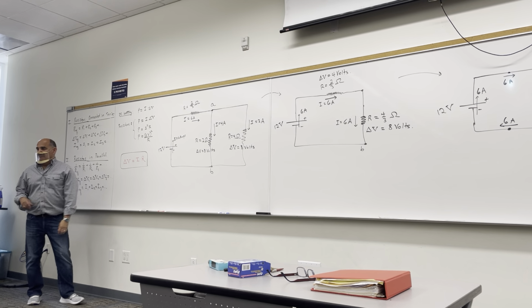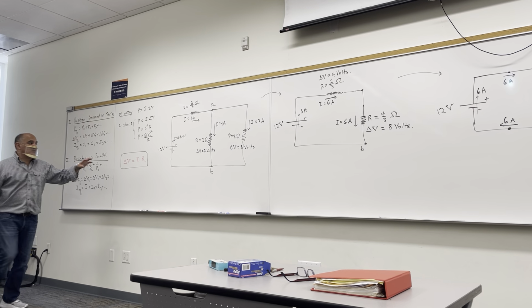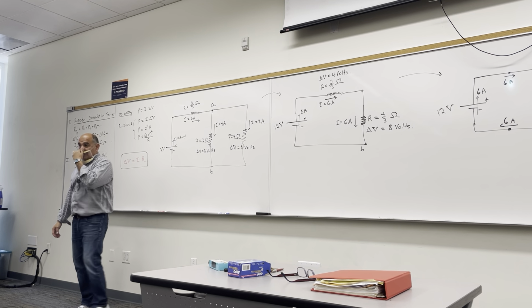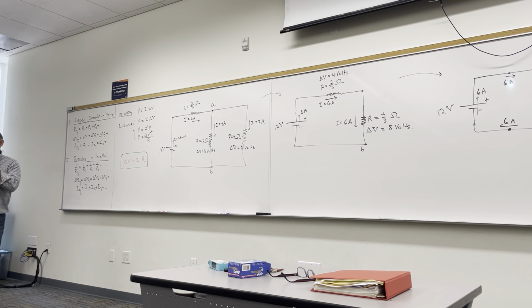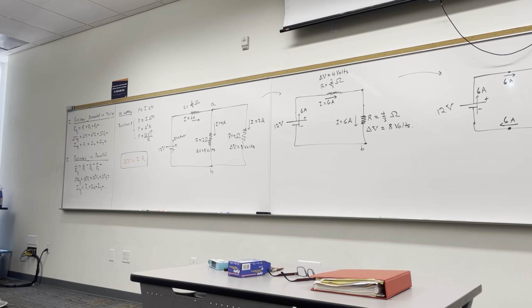Any questions? On the exam, do you want us to just draw that, or do you want us to box the answer? I'll give you the circuit, and you'll have to figure it out. By drawing it, it helps. Do you want to box the answer at the end, because there's a lot of numbers? Yeah, and you should draw big. You can write, current through the 2/3 ohm resistor, 6 amps, to the right. Current through the 2 ohm resistor, 4 amps down in the circuit, right? And the current through the 4 ohm resistor is 2 amps down. You can then box that.